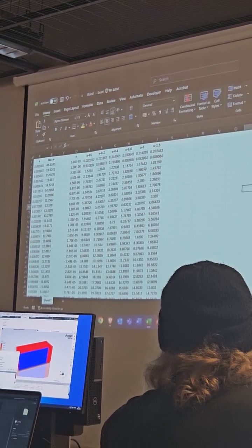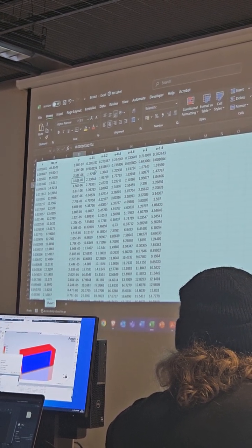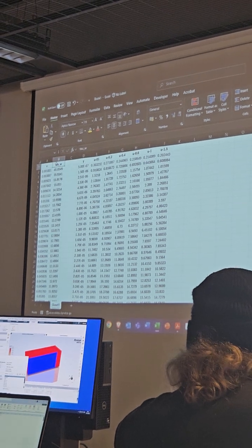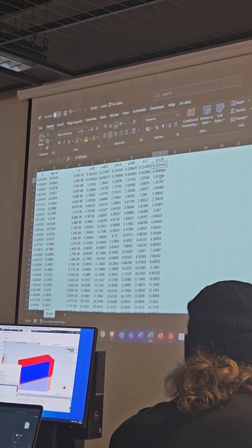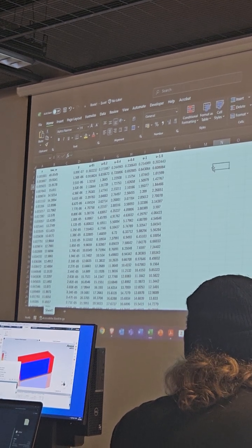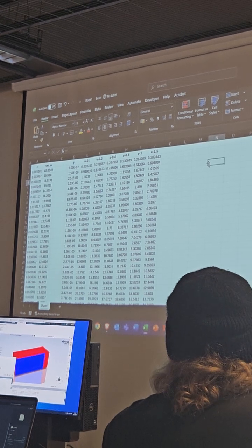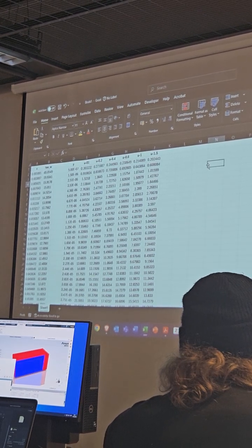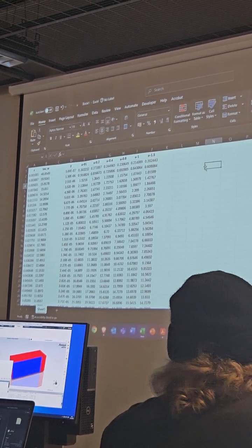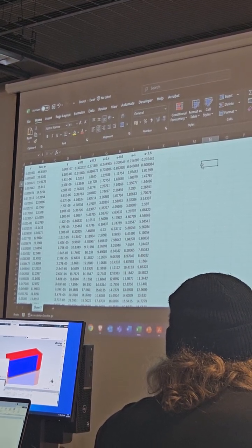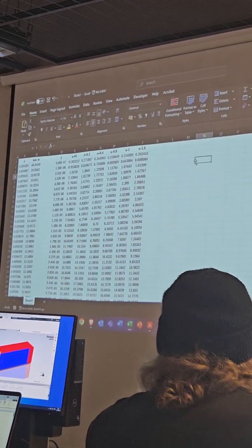So I get just this kind of distribution over here. x versus tau wall, y versus the velocity distribution at different x values. So then the next thing we can do is to calculate the Reynolds theta. For Reynolds theta, we need theta.